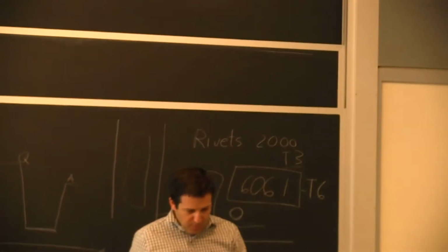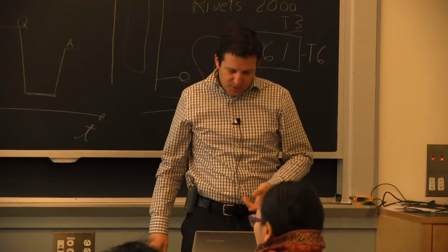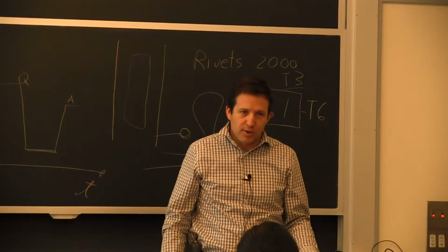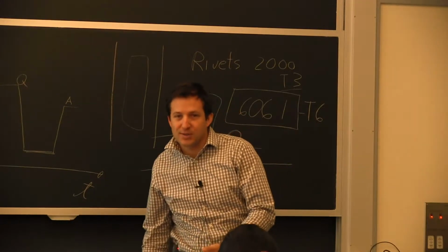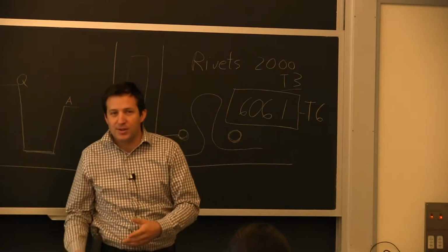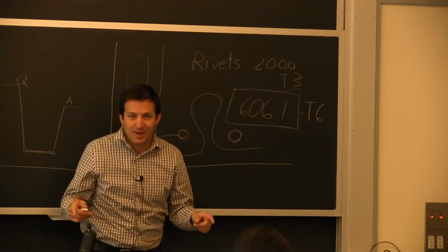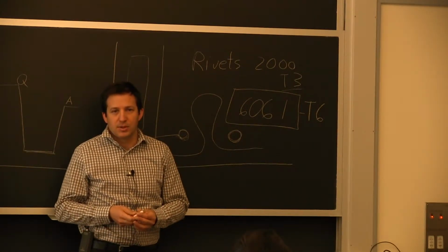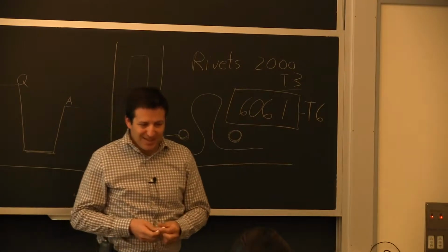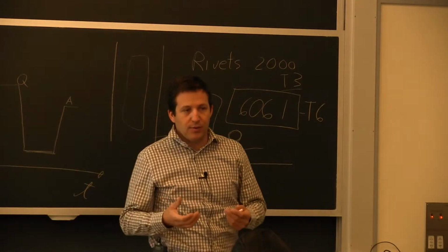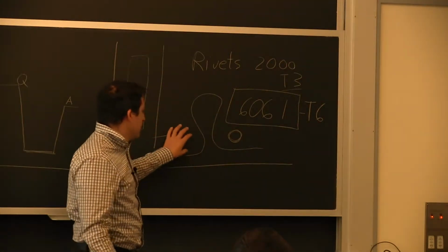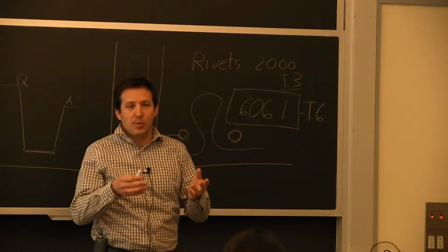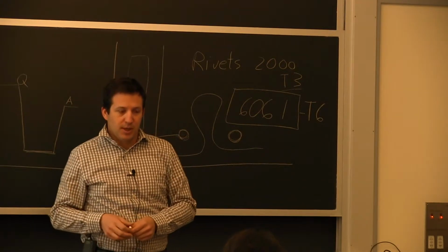Part of this experiment was really to show you can gain more information if you're doing a scratch as opposed to if you do a hardness test, because when I went to the lab and ran the hardness test, I got the same number, but when I run this test, I see a bigger difference between them. So it's a test that's very sensitive to hardening of the material, which relates to whether the precipitates are slightly smaller than the maximum hardness or slightly bigger.